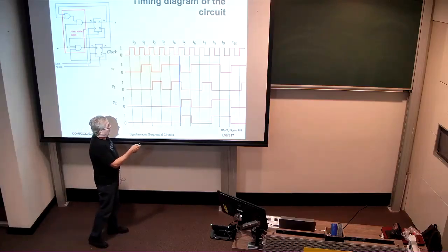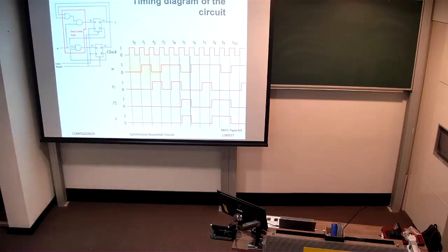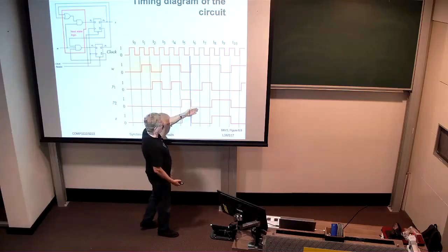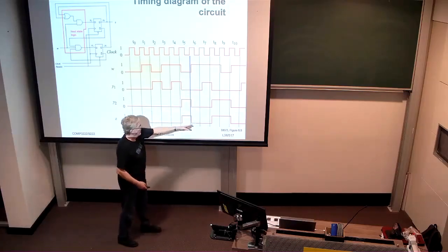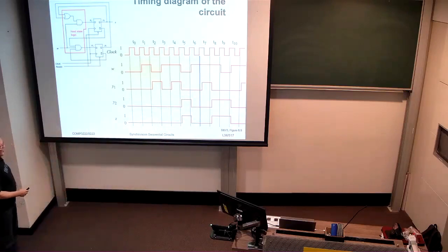So when we have the upper flip-flop being 1, of course, our output Z goes to 1 as well. But on the next rising clock edge, W is 0 again, and therefore the whole system resets. We go back to a state of 0, 0, the output being 0. And on the next rising clock edge, we see that W is 1 again. So again, we go into the state 0, 1. We see a second 1 and therefore go into the state 1, 0 with the output being 1.